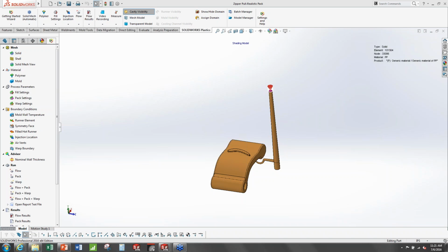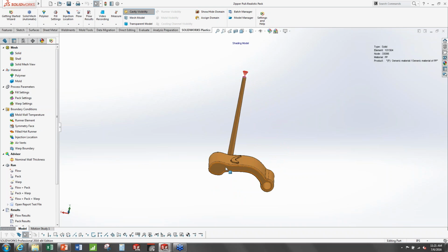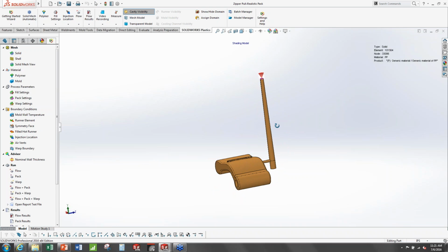This was a scenario where the injection molder was being called out by their customer saying, hey, you need to get rid of these sink marks. The molder was saying, well, it's based on part design. So pretty much what happened is running simulation to see if there could be an improvement, and if there could not be improvement. What we have here is a small part. It's basically a zipper pull where you grab a hold of the back section and it's attached to either a zipper or something like that.